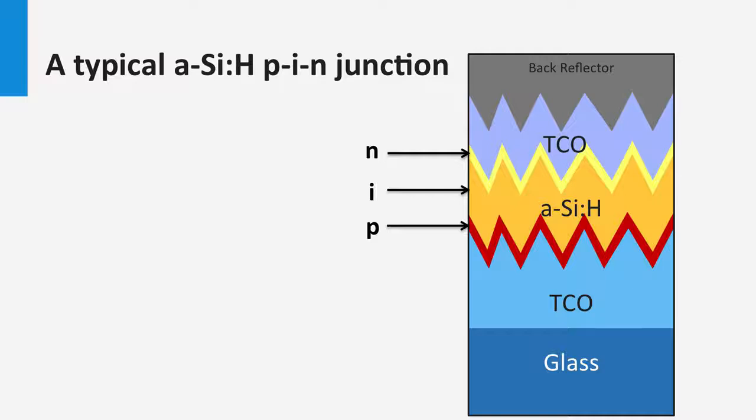P-doped layers are boron-doped amorphous silicon, but also the higher bandgap materials as boron-doped silicon carbide and silicon oxide layers are used to enhance the transmission of the bluish light into the absorber layer. As back reflector, usually a TCO metal back reflector is integrated into the device. Metals are either aluminum or the more expensive silver, which has a higher back reflection compared to aluminum.